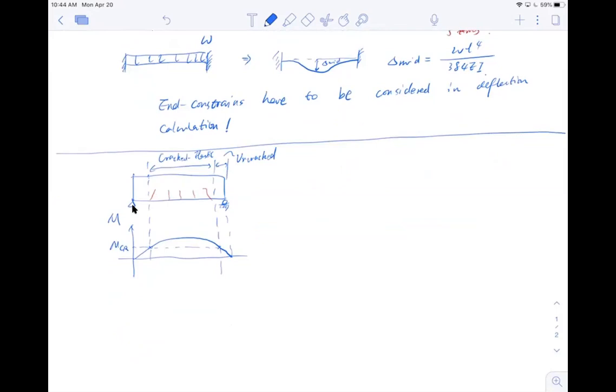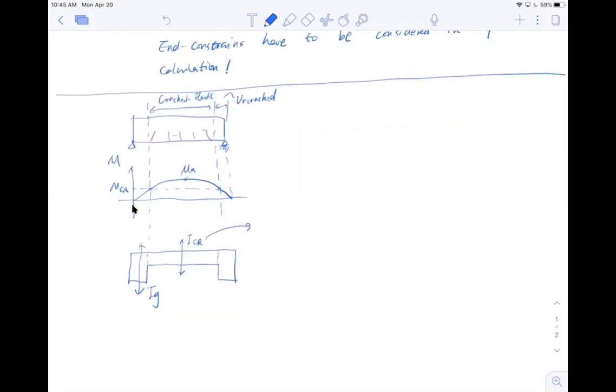Now, if I have 2 different stages or sections when they crack, when the surface load is applied, and this is the applied moment right here. What I actually see is 2 sections. One's a little bit thicker, remember when I transformed that, and the other is a little bit thinner. So this is uncracked, and this is Ig. This is cracked, and this is the compressive zone, and this is the equivalent bar area underneath it, remember? And this is the whole thing with the little wings on the outside.